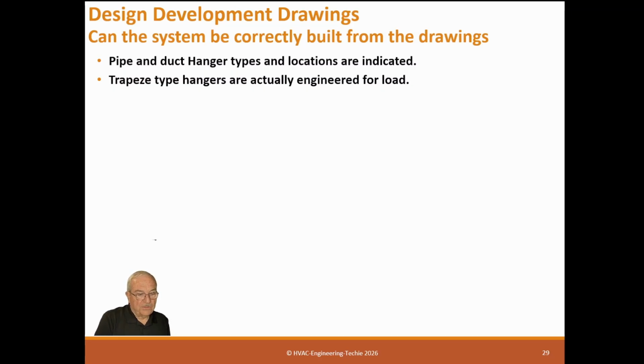And there's also this thing, standard codes don't allow electrical to share hangers with anybody else, which is a good thing because some contractors get really heavy, unless it's engineered. Unless you have a hanger that's engineered to hang both mechanical and electrical off the same device and has been engineered for that load, then I think the code may accept it, may not though.